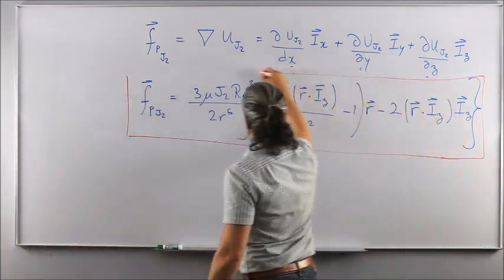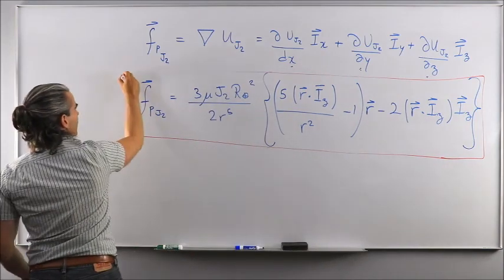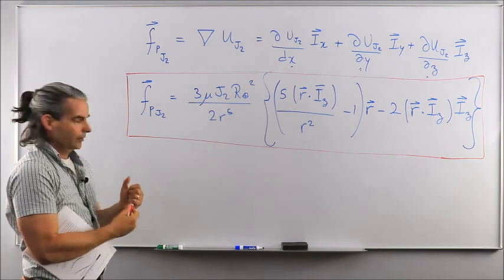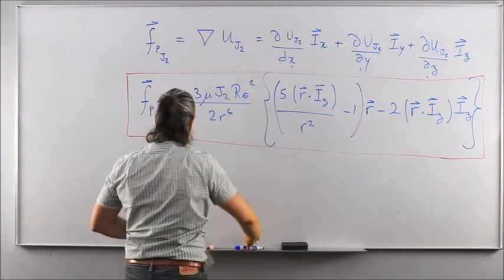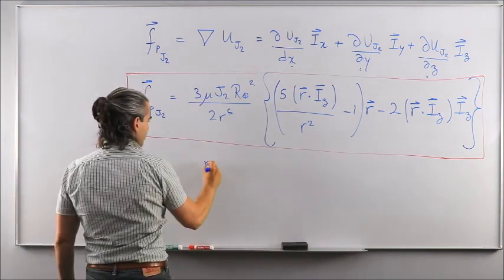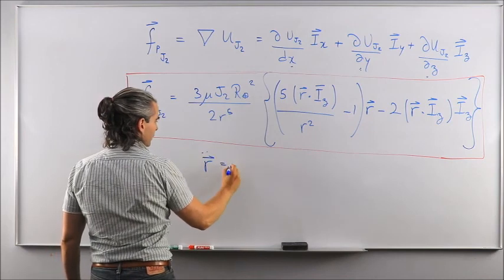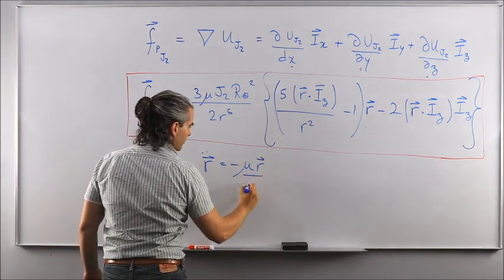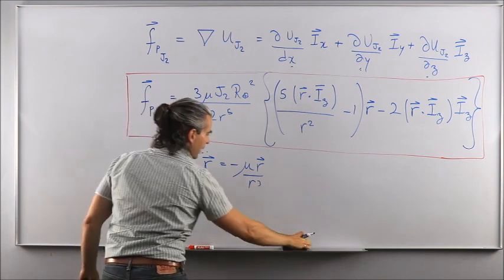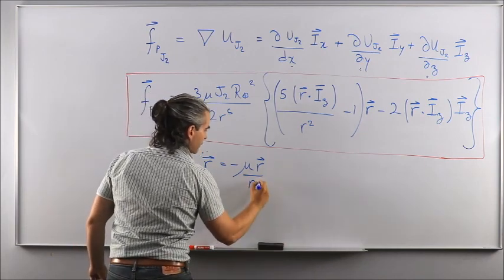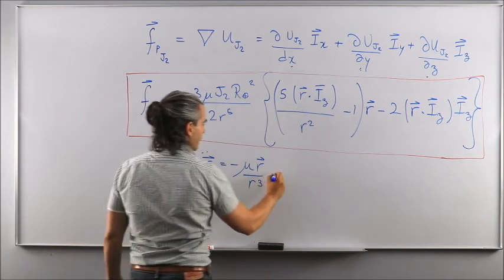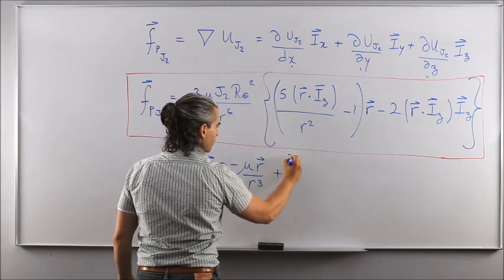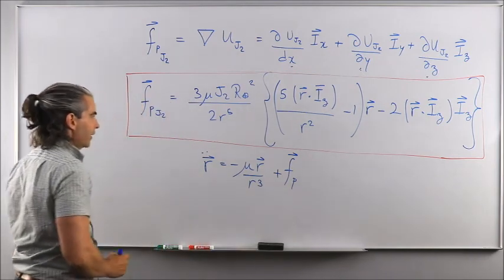So this result quantifies the perturbing acceleration due to J2 on our spacecraft. Right? So remember when I had written a while ago our equation of motion for a spacecraft orbiting a primary body. That's what we had. I had said, well, you can make it more accurate by adding perturbing acceleration terms like that, FP.